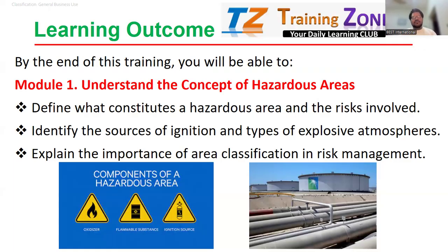Proactive means before something happens, before any incident or accident happens, we have to do risk assessment, we have to identify the hazardous areas related to the hazards and the risk also, and make our control plans, implement those controls, perform our toolbox meetings, have gas testing, even gas testing before issuing the permit, even before first entry.